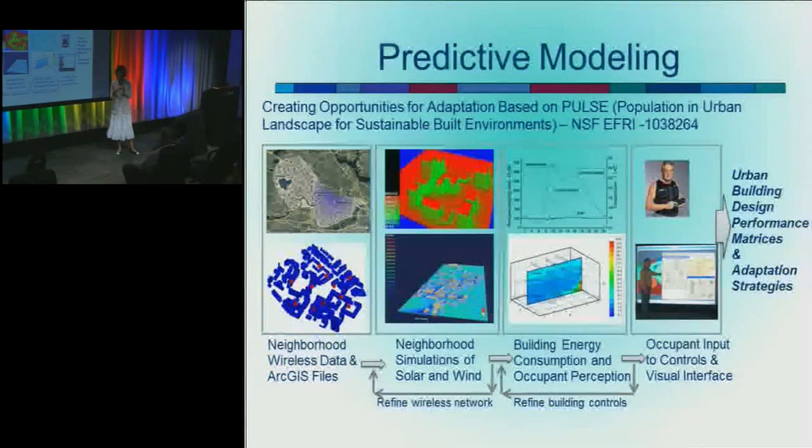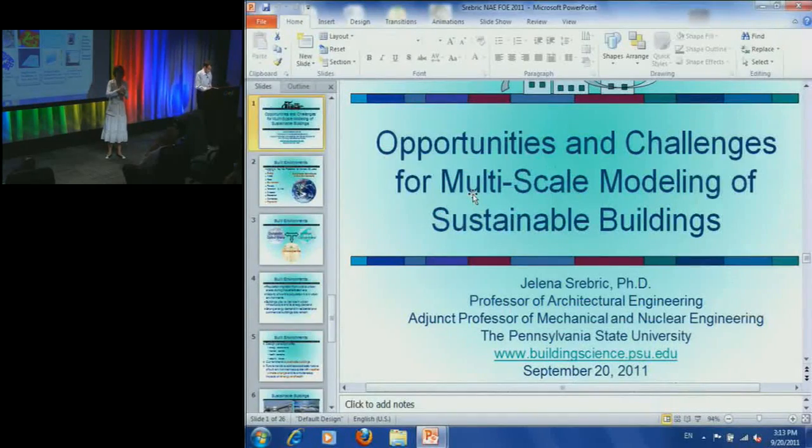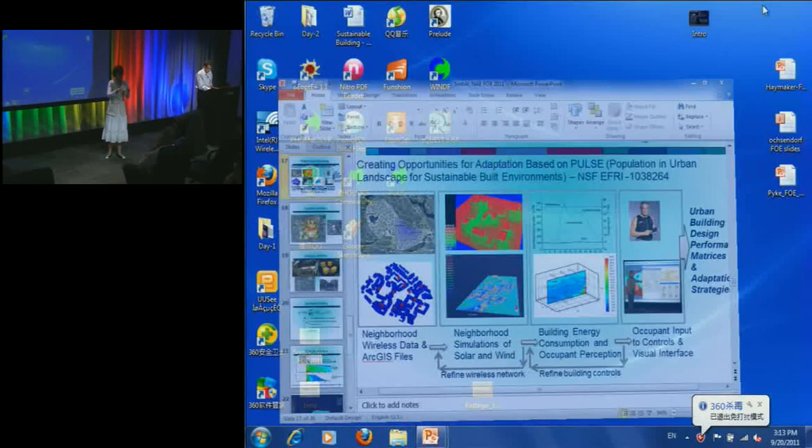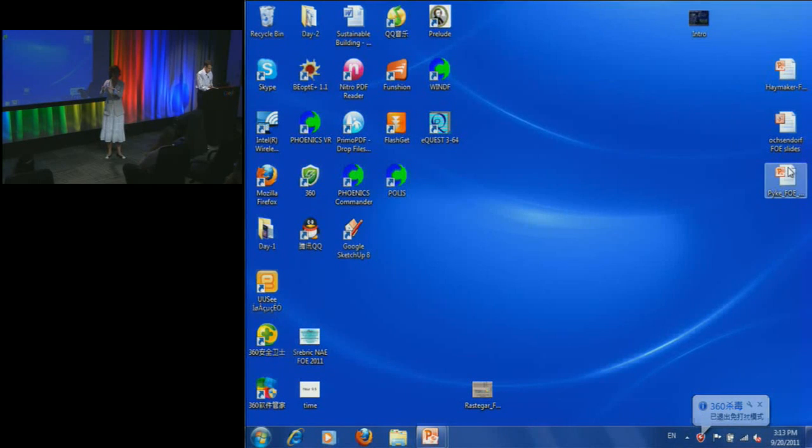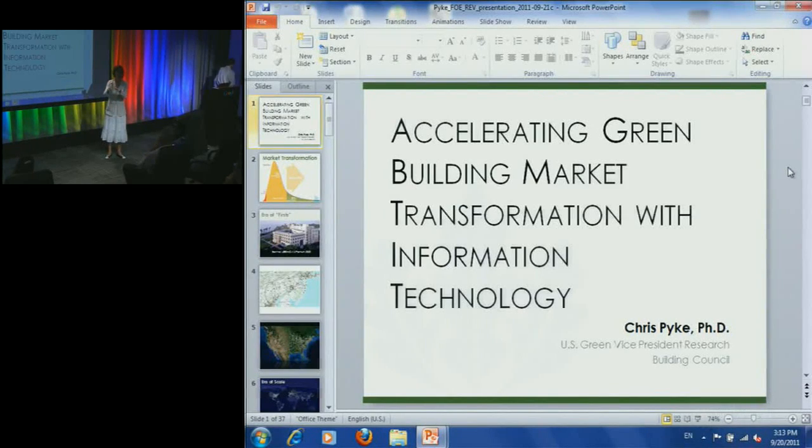So what we can do is we can somewhat predict how your building will be occupied and try to jumpstart mechanical systems. And the reason why those systems are slow, the way we do the generation of cooling capacity and rejection, the whole process is roughly 100, 150 years old. We are right now starting to see some innovations, but what you are using in standard buildings is a pretty inert, very old system. We changed the refrigerants a little bit and some aspects of the cooling or heating systems, but it's pretty old technology. We don't have better ways of generating cooling and heating capacity yet, or faster ways. You can use electricity, for example, for heating, but that's outrageously expensive.